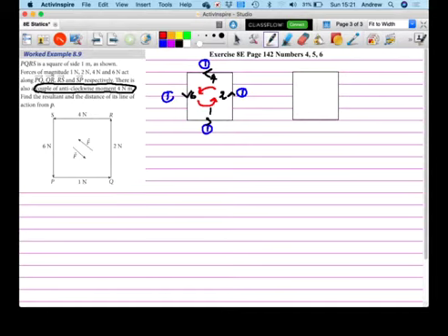There is just a moment of value 4 Newton meters in the anti-clockwise direction. Don't forget, when you do the resultant for a moment, because the two forces are equal and opposite, they cancel each other out. And that's why you don't need to know where the couple is on the diagram, because when you're working out the resultant forces, it's going to cancel out anyway.